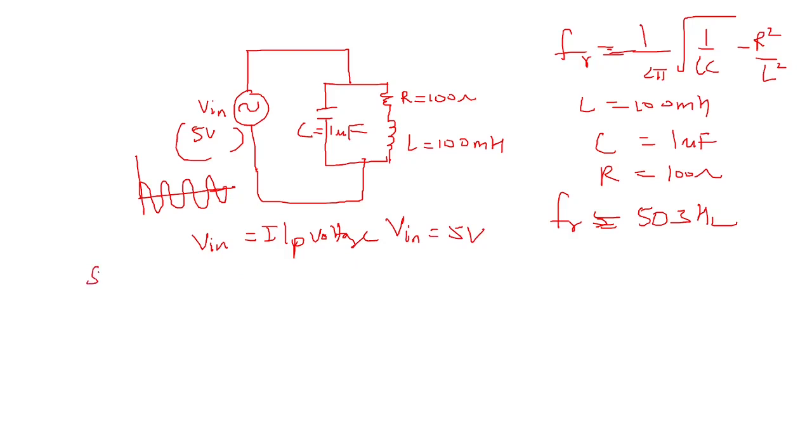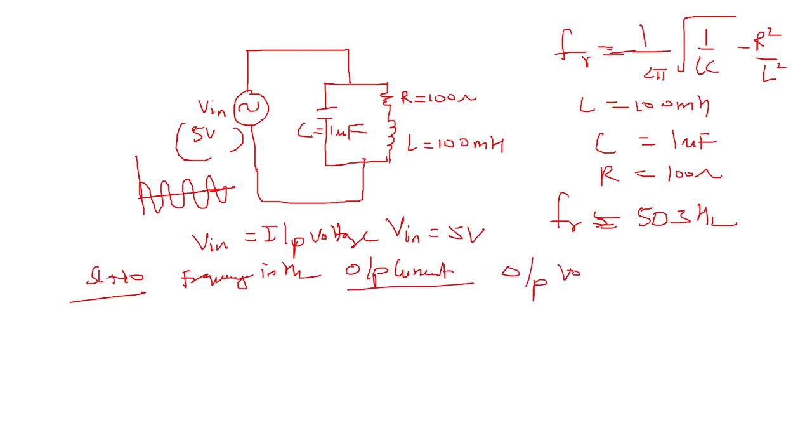You can have the columns as serial number, frequency in hertz, output current, and output voltage. You can put a meter to see the current through the circuit, and also check the output voltage by connecting it to a CRO.